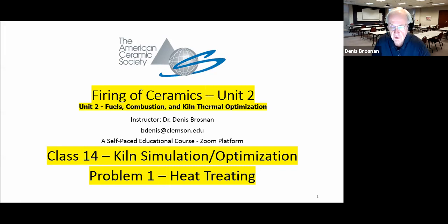Okay, so we've looked at heat flow as a simulation of furnace walls or other parts of furnaces. We have some environmental conditions. We select our products and we arrange the products in layers, if you will, multi-component linings, and we're able to compute the heat loss and heat storage and something about the expected temperatures at interfaces and at the outside shell of the furnace. We used eSolutions to do the same thing.